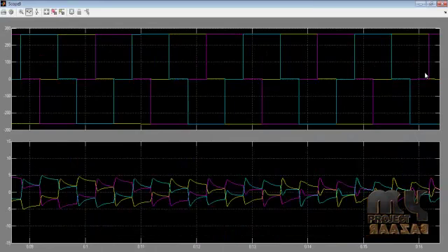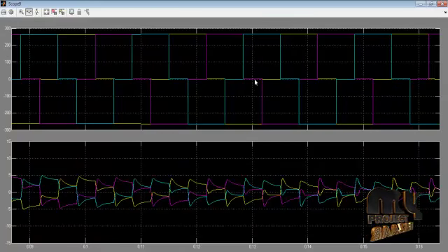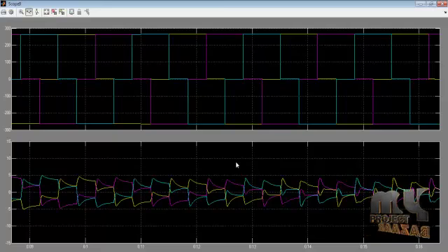And next one is the nonlinear load waveforms. So here we can see the nonlinear output current waveform is not a sine waveform, and this is the output voltage waveform. The voltage is also around 250 volt. So using a nonlinear load, the sinusoidal output current is not obtained, and this also affects the harmonics and injects harmonic current. Due to this kind of waveform, we implement a STATCOM or other shunt active filters to recover this current waveform into a sinusoid.